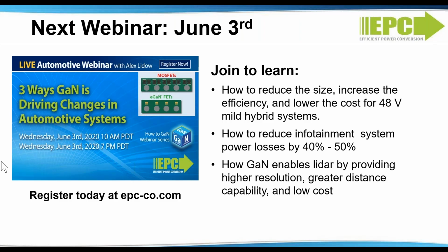What controller are you using on the secondary side? You don't need to add one on the secondary side because we use one controller for both the primary and the secondary. I assume you're asking about the LLC converter. The LLC converter is well defined, and thus you really don't need to operate it using a dedicated synchronous rectifier controller.